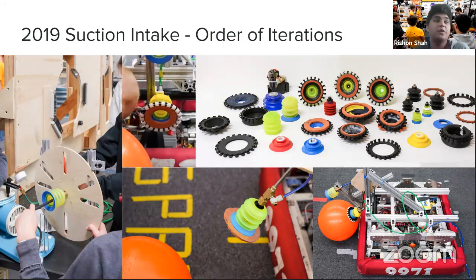Another variable that we messed around with were the bellows. Basically, those are the green squishy areas of the suction cups. And we just wanted to see whether those bellows were actually necessary for the suction cups to perform. So we tested that by squishing them down and then taping them together, and testing the suction cups as normal besides that. And we learned pretty quickly that the bellows were necessary for the suction cups. But it's just an example of how testing individual variables is really important because it gives you valuable information.